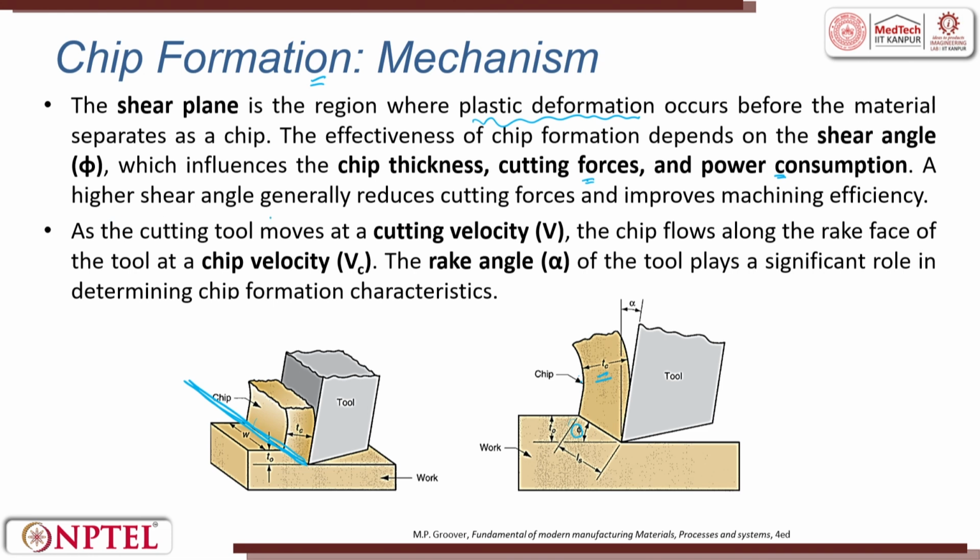A higher shear plane angle generally reduces cutting force and improves machining efficiency. When is the shear plane angle higher? When phi is large, you will have reduced cutting force, which improves efficiency. Shear plane angle high, then forces are less. Because the forces are less, the power is also less. Force and power are directly proportional. When the force is high, the power also will be high.